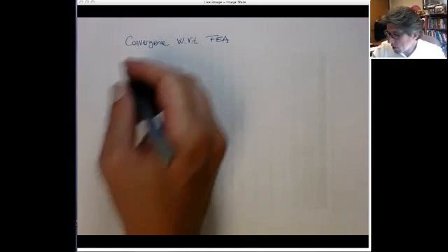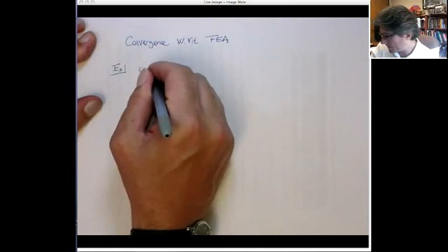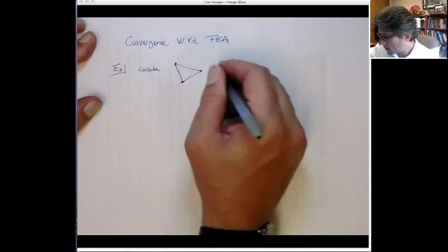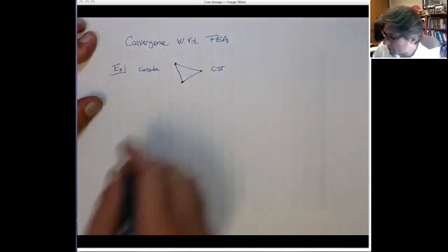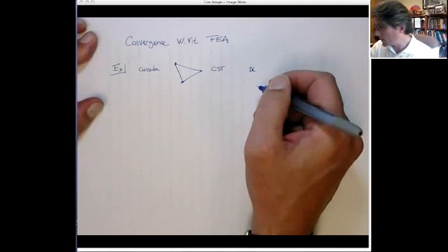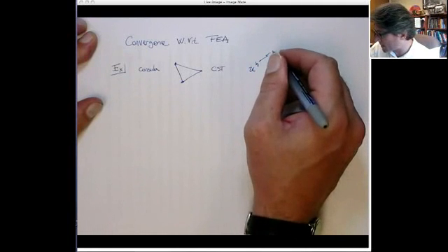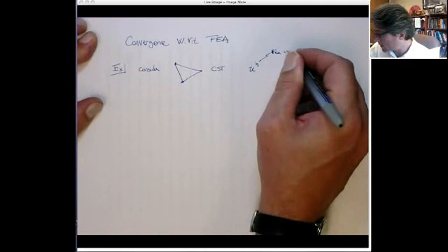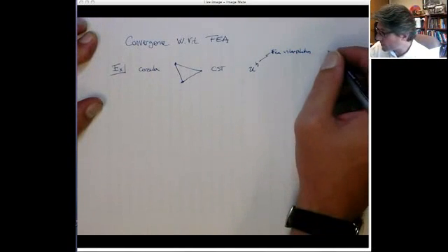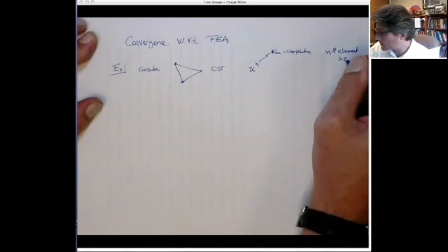So we know. Let's do an example. And I think this shows it the easiest way. Let's consider our good friend the constant strain triangle. For the constant strain triangle, we know that it's linearly complete in the displacement. So the displacement, I'm going to put a superscript S to denote that this is an approximation. This is the FEA interpolation, okay? And usually it's a function of h, where h is kind of thought to be related to the element size.